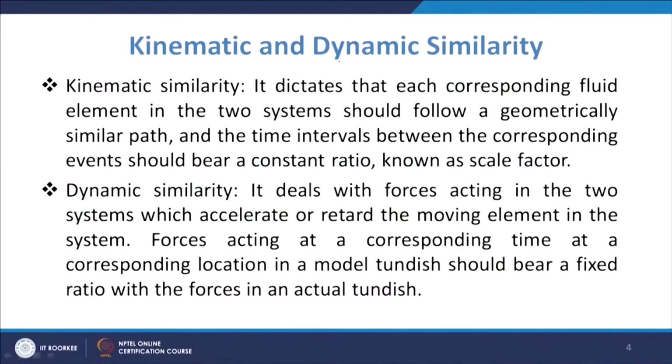Then comes the dynamic similarity. Now, dynamic similarity talks about the forces acting in the two systems. In kinematic similarity we are not talking about the forces. However, in the dynamic similarity we will be talking about the forces which act in the two systems, which accelerate or retard the moving element in the system.